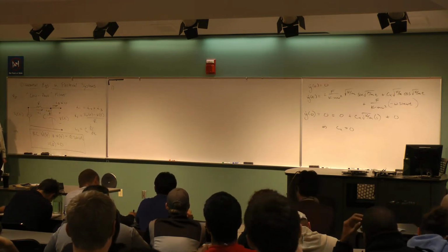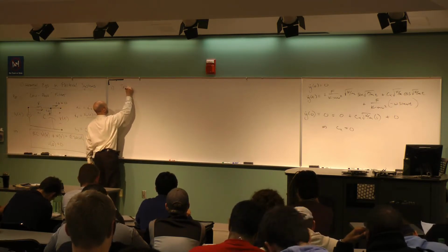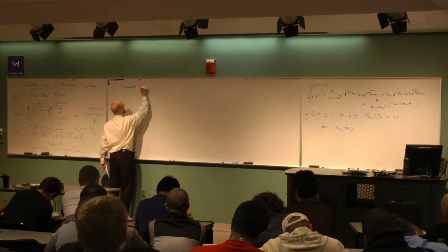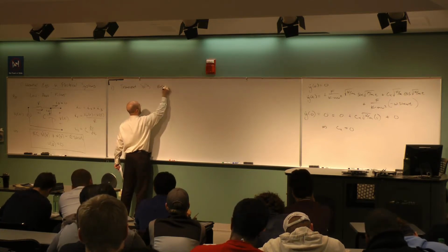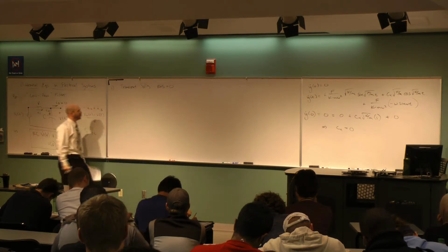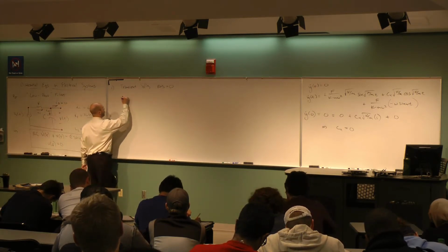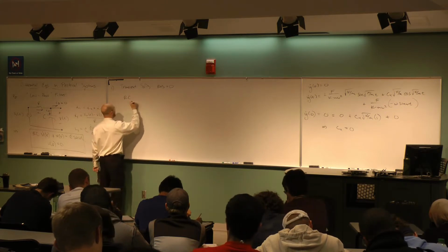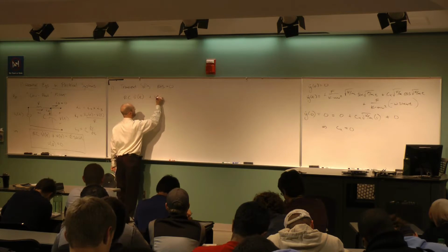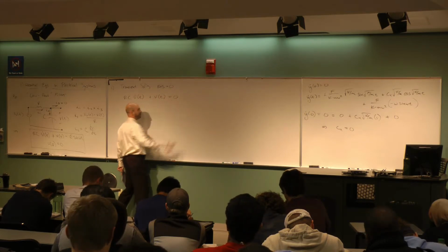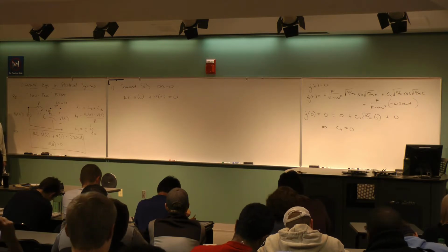Set the input equal to 0 because I'm finding the transient solution. So let's set the right-hand side equal to 0, which is the input function. Great, no input. What I have now is RC times V dot, that's the derivative, plus V of t, and that is now equal to 0. Excellent. Next step.